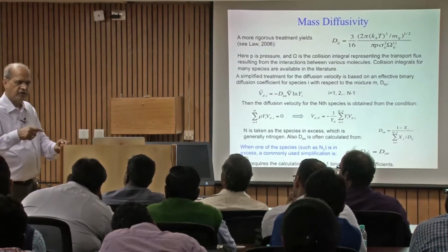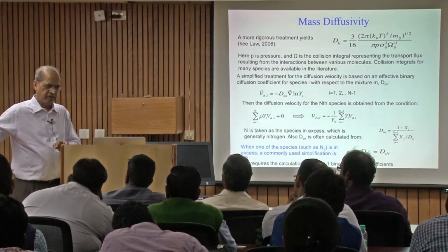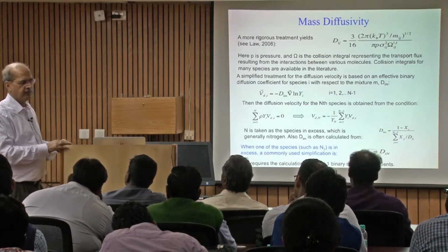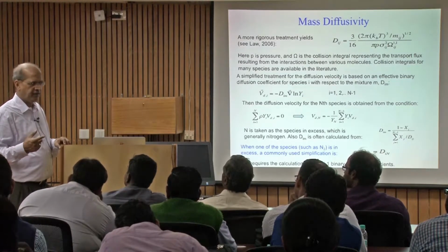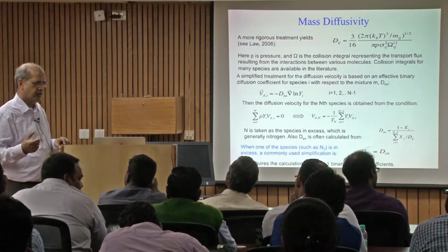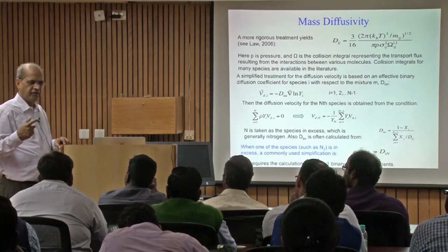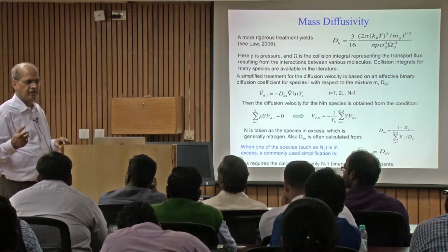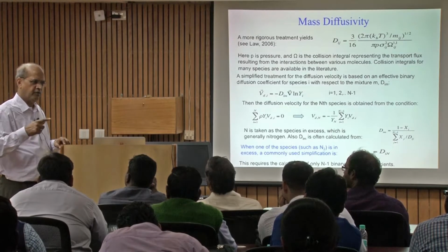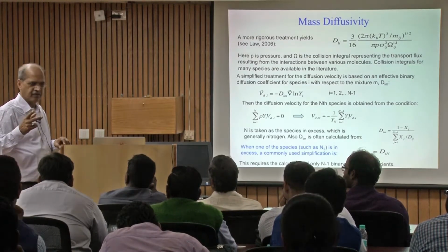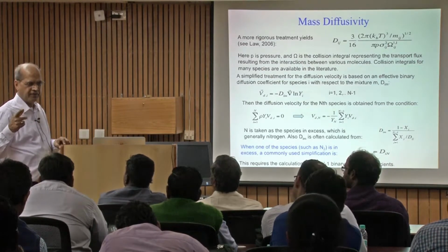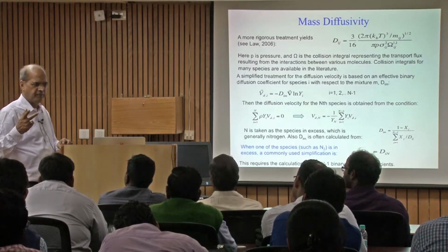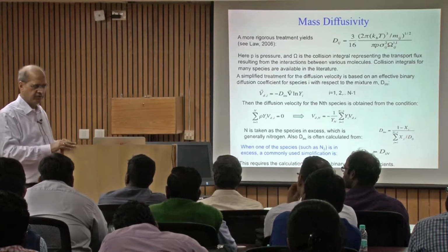We can calculate, I think we will do some calculation in the next session. So the fuel is about 5%, then 95% is air. And out of that 95%, oxygen is about 20% of that, right? So 80% of 95% is about 70-plus percent, and that's nitrogen.